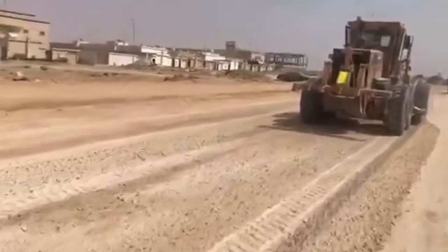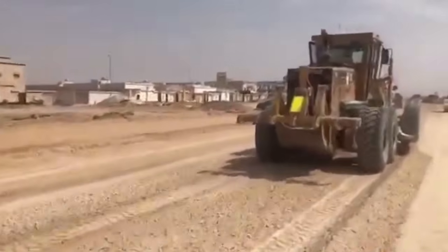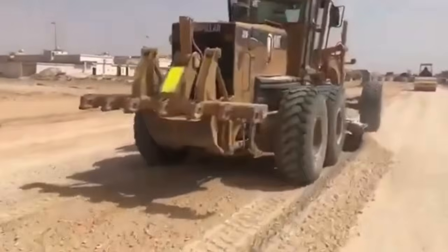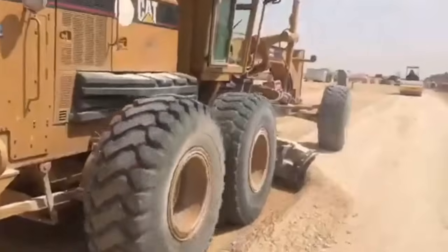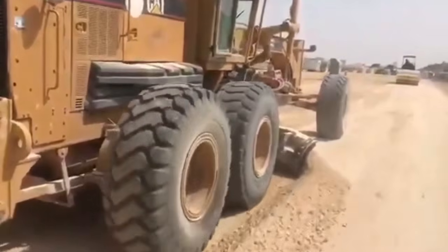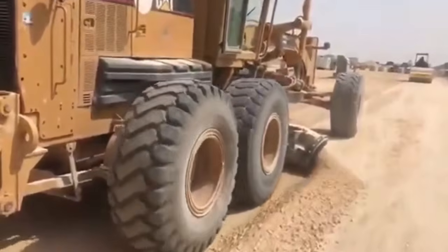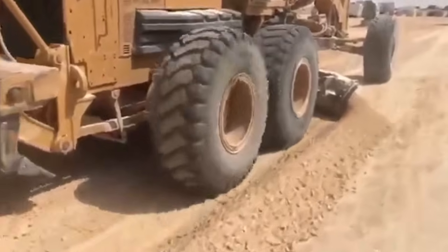For checking compliance with the above requirement, measurements of the surface levels shall be taken on a grid of 10 meters longitudinally and 3.5 meters transversely along the pavement. The average of 10 measurements shall not be more than 3 mm above the permitted limit.